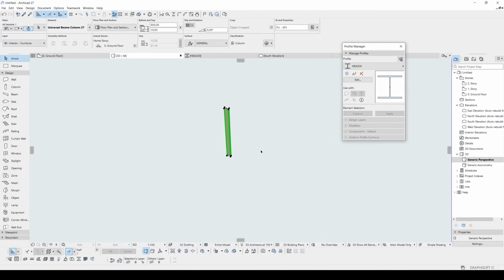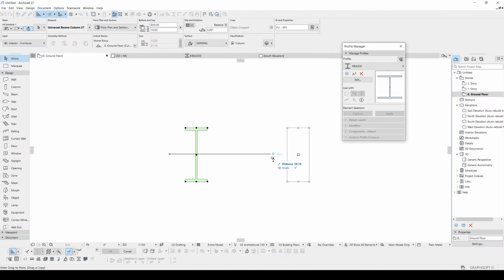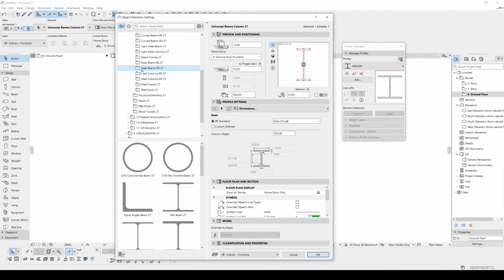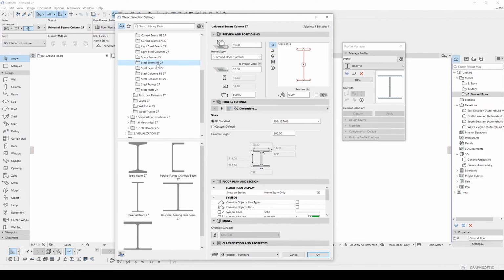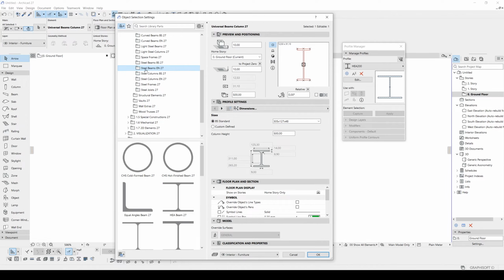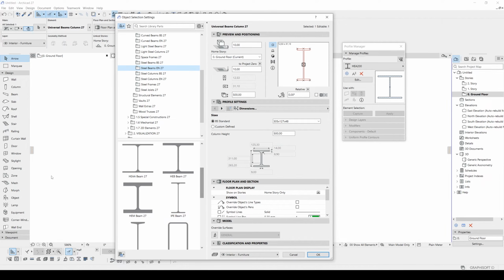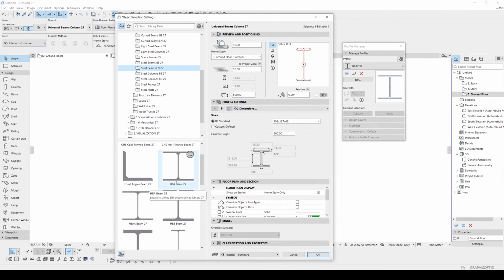And after that, let's say that we will duplicate this as 750 centimeters, and after that we are going to add a beam. Therefore I'm going to duplicate this from the settings. I'm going to choose steel beams, but not BS, it's going to be EN, and we can see the profile names. These are universal names as we place in the columns. For instance, HEA beam maybe.